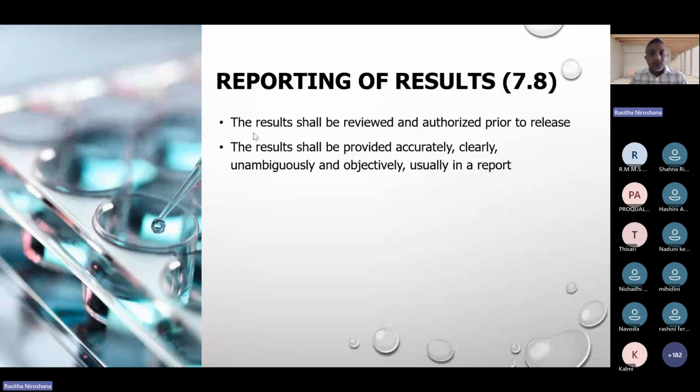And then you take the pH meter outside at the effluent treatment plant (ETP) and measure the pH at that particular temperature. So the uncertainty factors are totally different, right? When you do the uncertainty calculation, the environmental uncertainty for the lab is very minimal, but the environmental uncertainty outside can vary seriously. So these things are related, right? You can't just look at it as a documented requirement. It's not only a documented requirement, it is a different kind of requirement as well.